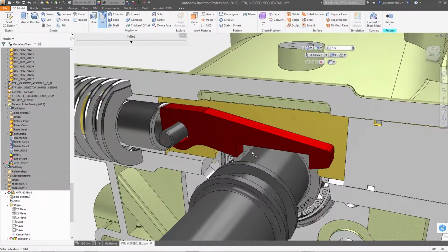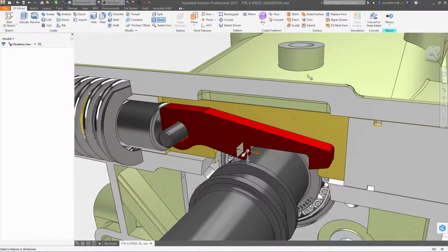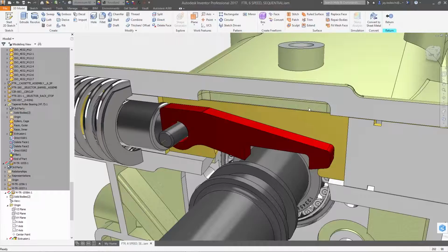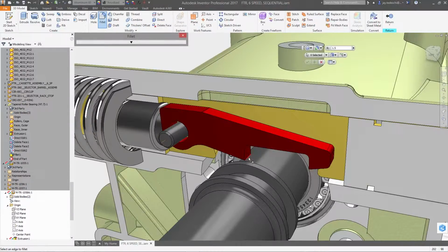Features like fillets and chamfers can be added by selecting an edge of the part and picking the command you want. Again, you can use the handles to adjust the size visually or key in exact dimensions in the mini toolbar. By nature, the design process is iterative.